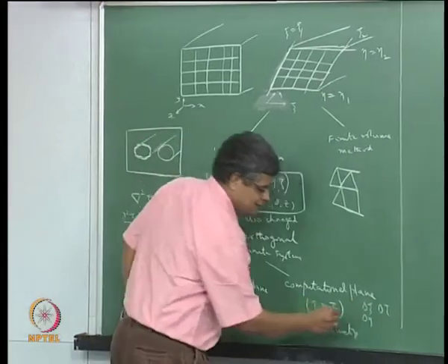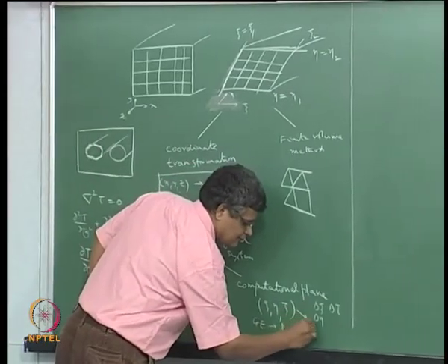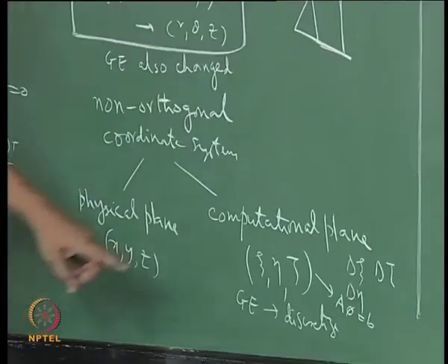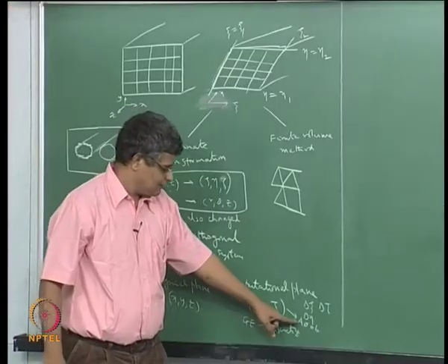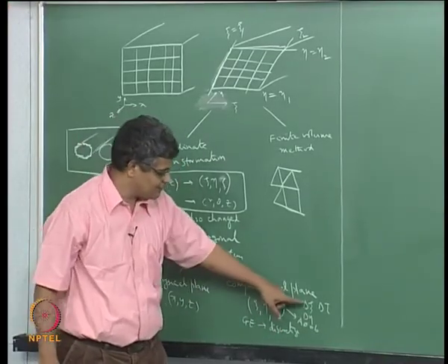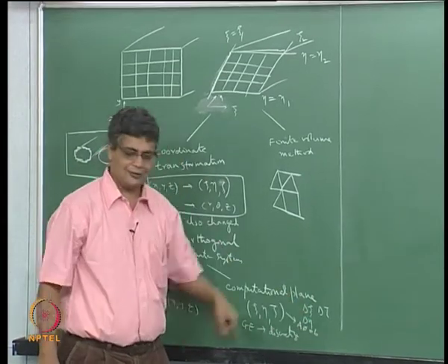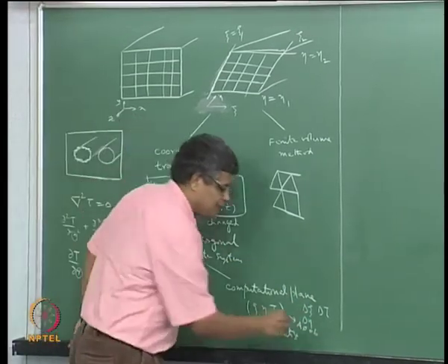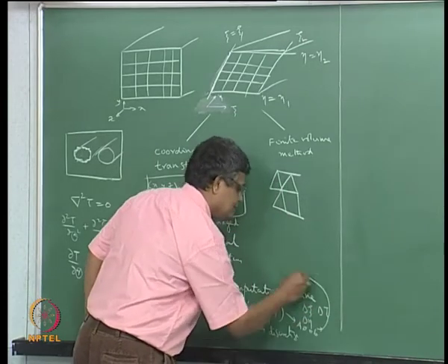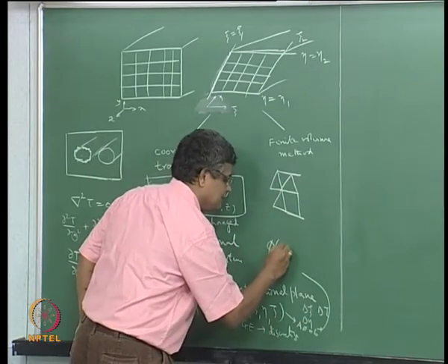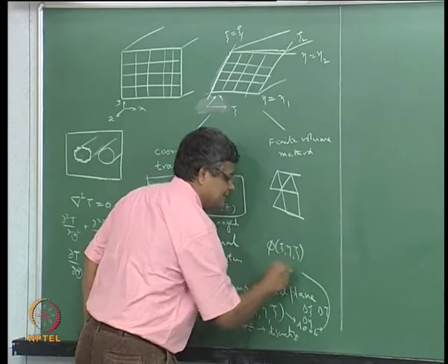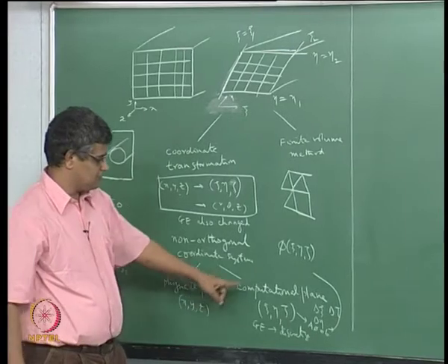So from these we convert the governing equations into A phi equal to b, where A consists of these, instead of delta x, delta y, delta z, we have now delta xi, delta eta and all these things. And then we finally get, by solving this, phi at every xi, eta, zeta that we wanted.